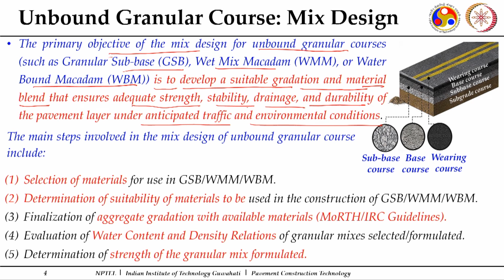Now, if we put down some of the steps involved, first of all, for any mix which needs to be designed, you require materials which can be used in that particular mix. So, selection of materials, and definitely you have to rely on the available resources nearby, because you cannot bring materials from very far away, it increases the cost.